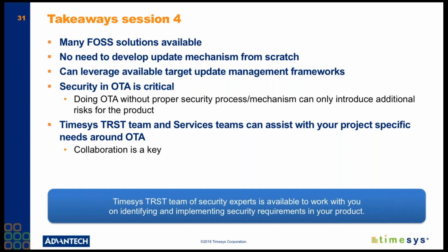I'm sorry, Teresa, could you repeat that question again, please? Yes, it's a long question. How do you ensure atomic updates when your microcontroller hardware requires an erase-before-flash method of update? And then the second part is, and your space is limited to one partition, or is this not possible?